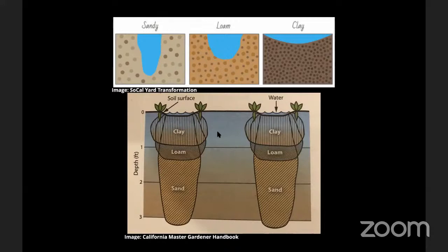And so if we are trying to get an even, deep soak in our drip grid irrigation system, that means we will probably need to put out a faster volume of water into one spot in sandy soil, so that we force that water to spread out a little bit more. And we know that it's going to have no problem just trickling down over time.